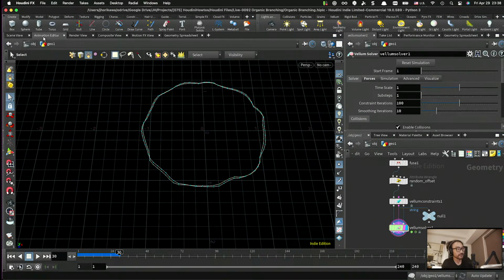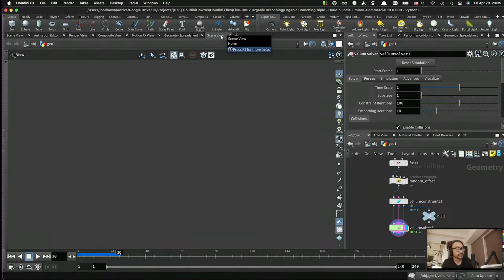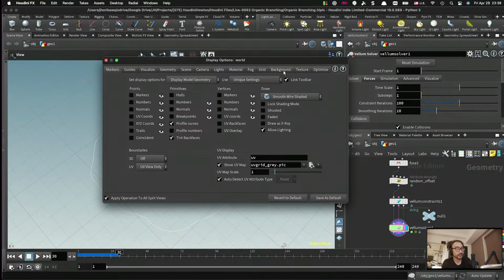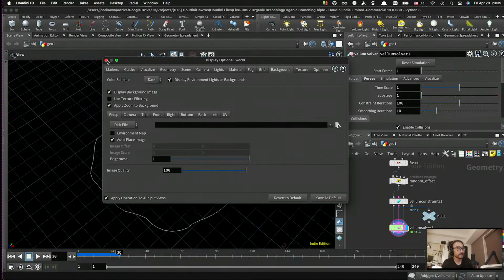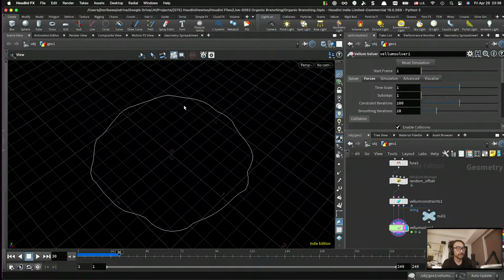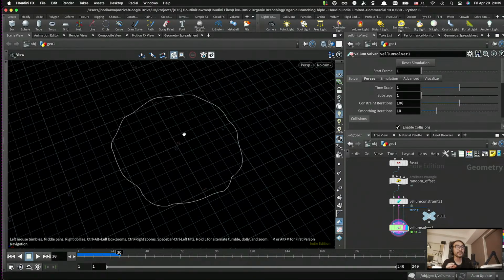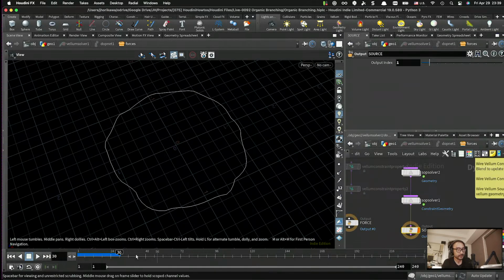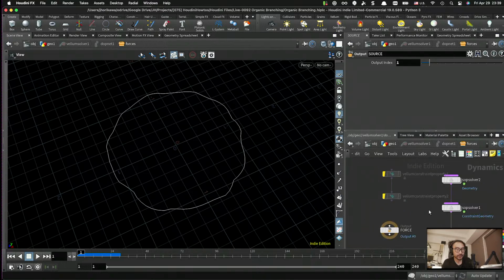I think it's just a cache here, which I don't really know how to delete, so I'm going to open a new scene view which will remove the cache, just like that. Remove the old view. I don't know the other way to remove this cache starting from Houdini 19. This happens to me. I'm not sure if that's the same for you guys.